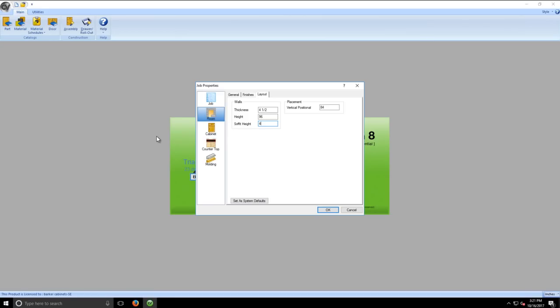And the nice thing about that is, let's just say the ceiling is out by 1 inch. And when I say that, from the left to the right, over say like an 8-foot range, the ceiling has dropped, say, an inch from one side to another. It's pretty common. But if you only have like a 1-inch tall molding, imagine if it drops 1 inch and your cabinets are perfectly level, which they should be, and it drops 1 inch from one side to another. That's not a good deal, because what's going to happen there is you're going to have a lot of molding, 1 inch of molding on one side, on the left side.